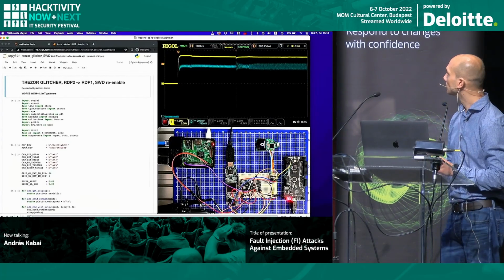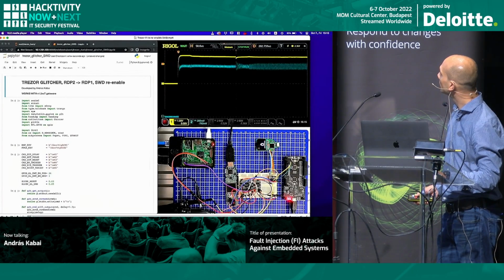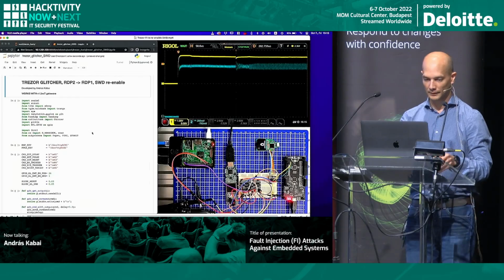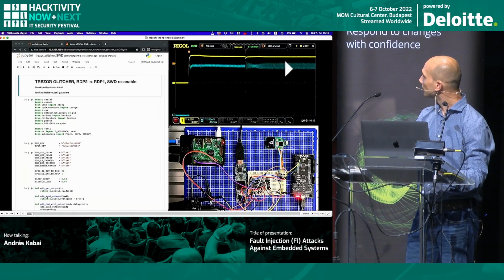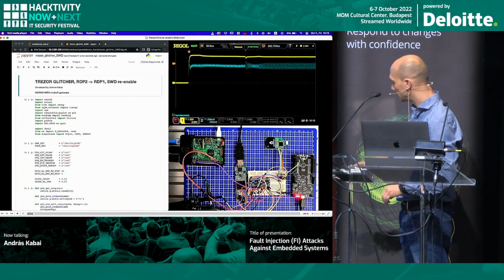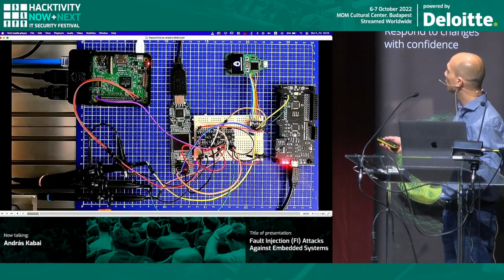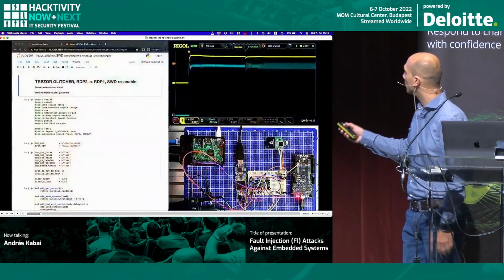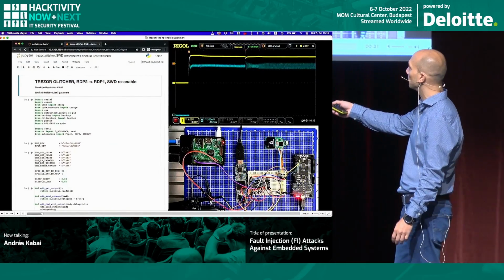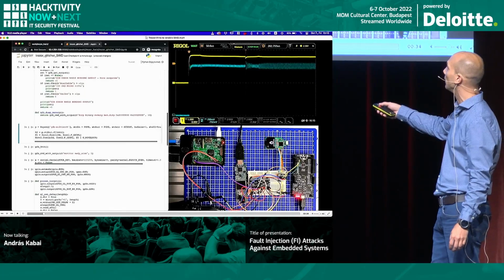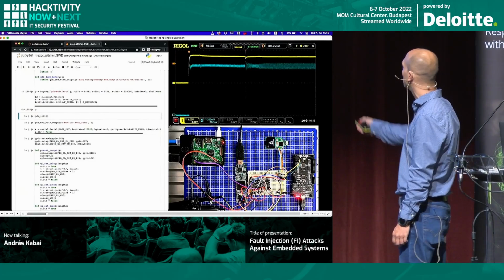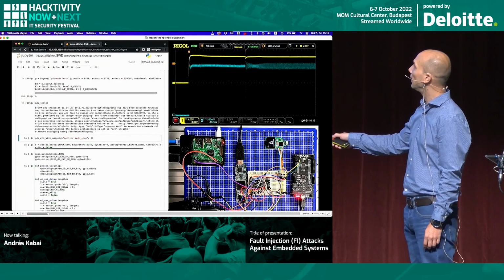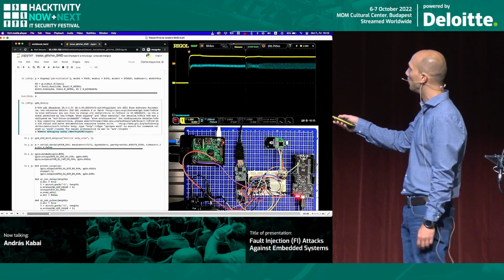So this is a test setup. The test setup contains basically the Jupyter notebook and the external camera for the target. What I do is basically walk through the custom code I implemented here, just executing it. This is just a function supporting the target. Here I open a GDB session to the remote service, and I'm just checking whether SWD is available at the moment or not.